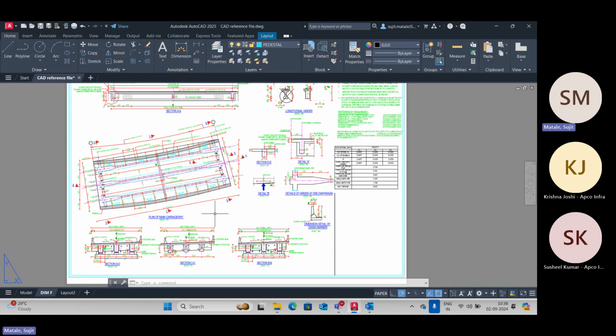In analysis also there might be different complexities: linear analysis, non-linear, geometric non-linear, material non-linear, first order geometric non-linear, second order geometric, and so on. We don't want to get into those discussions at the moment. Once that is done, it performs the analysis for us. As a user, what you need is the final results. As structural engineers, in practice, what we mainly look for are shear forces, bending moments, and axial forces. We extract those results and use our design methodologies as per our code provisions, and go for further design. So this is the workflow.